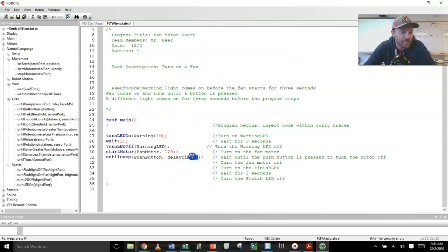Delay time. Now, this is really important. Because when you push a button, because of static electricity, when the connections get really, really close, it could trigger it. They call it bouncing. When you get close to closing the switch, the static electricity makes the computer think that it touches. So when you're pushing a button, you actually could be pushing it like 10 times, even though you're pushing it once.